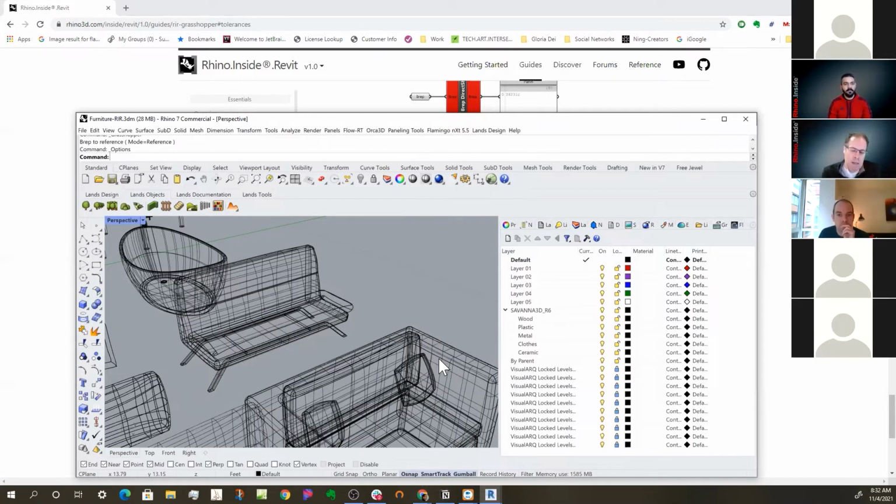We find that to be more forgiving because their SAT importer does a lot of massaging and adjusting of the model in order to get the model in. The drawback to that is it's slow. If you have 64,000 geometry objects in there, and it starts using SAT for all of them, all of a sudden you're going to find the transfer feels very, very slow.